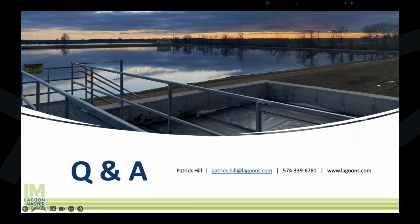If struggling with ammonia but no duckweed is present, are there other signs to look for? I think just testing the ammonia is the way to do it. And like I said, you could buy the Hach DR900 and do your own test. That's not too expensive. I think those are the big things. Ammonia will affect algae growth as well, but algae just tends to grow in lagoons anyway. So I think you just need to test your effluent ammonia.